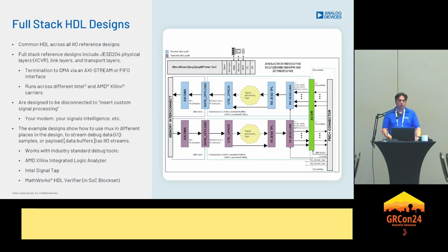We provide full-stack HDL designs. We call them reference designs. They all use the common HDL and I/O infrastructure. We typically terminate to DMA via AXI stream or FIFO type interfaces, and they run across different FPGA vendors, Intel, AMD.